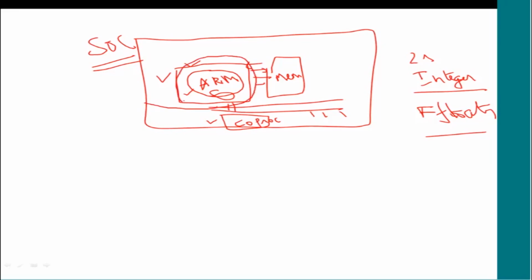If the coprocessor functionalities like floating point support were built into the ARM core, it would unnecessarily increase the size, power consumption and complexity of the chip in terms of area and power. We do not want a functionality inside the processor where it is not required.